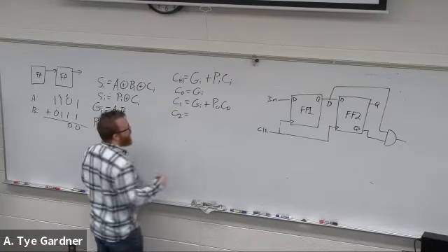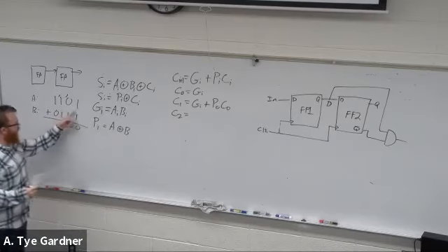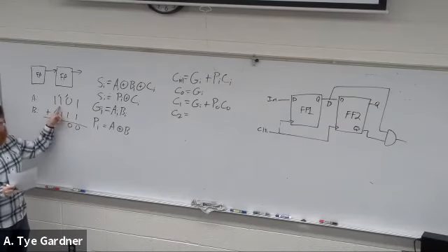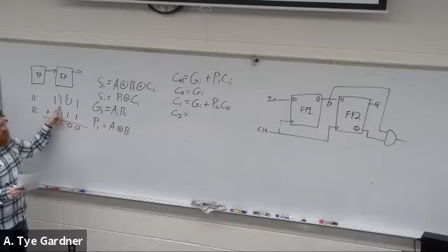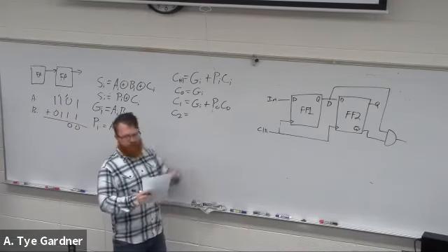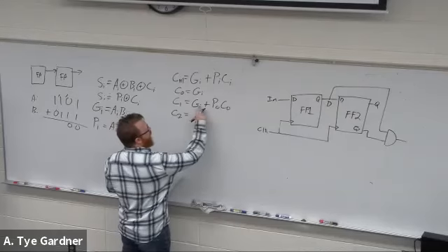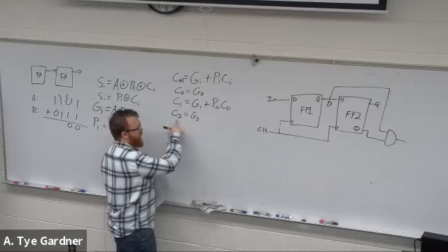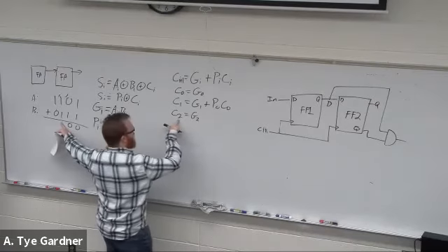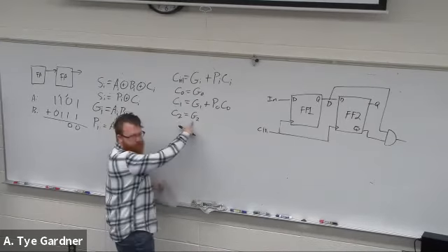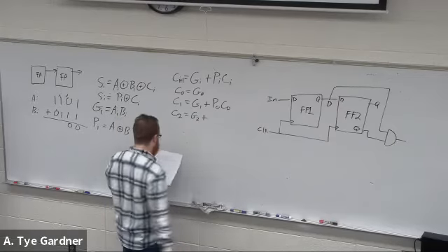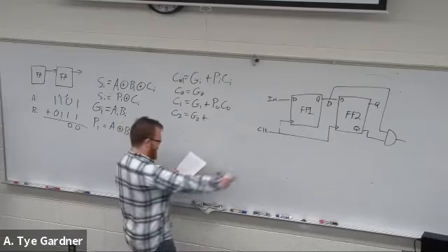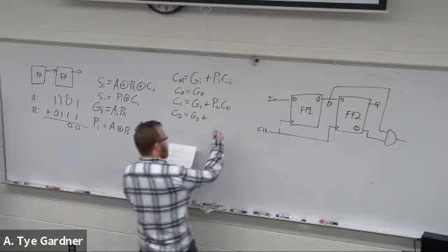Well, C2. Unfortunately, C2 now has to look all the way back here because he created a carry, this one generated it, it got propagated, right? Now this propagation carry. So it's looking at this P0 going, okay, we could have a problem. I guess I could write this as C1, G0. That now third column, which is carry 2, is saying, did I make one? Or did this happen? Let me just actually write this out.